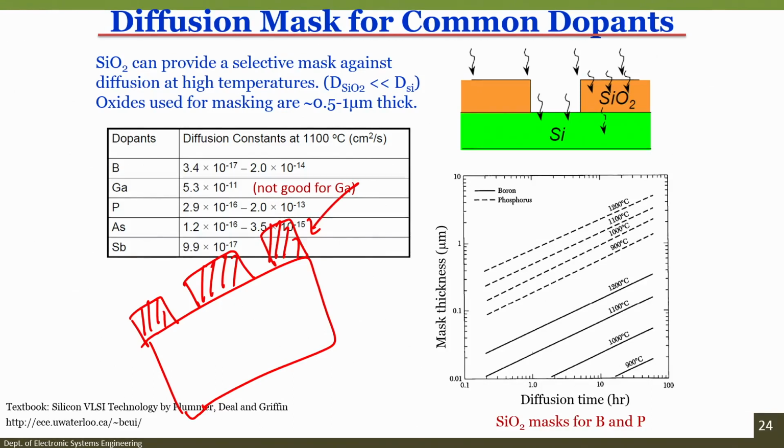We will see photolithography in the next module, so do not worry about it. So, these are silicon dioxide patterned on a silicon wafer. Now, what I will do is dope this silicon, because here SiO2 is not present, with, let us say, boron. If it is an N type silicon, I will dope this silicon with boron. So, what will happen? I will form source and drain.